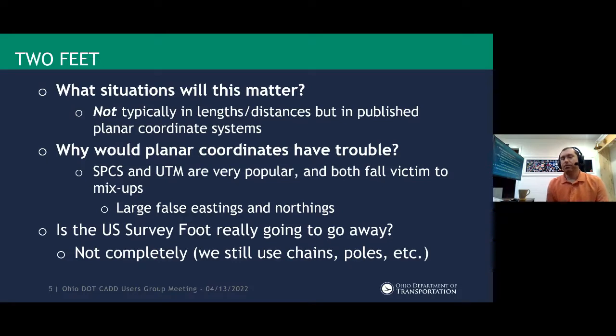And this stems back to, like I said, the change to the NSRS and the standardization that's happening. This is really trying to clarify and clear up all of the differences that have happened throughout the history of that foot definition. It goes back to, I believe, 1959, when they made the change to the international foot for all other types of measurement, besides that exception for the geodetic applications in surveying. That's where that foot definition has stayed. So this is clearing up all of that history.